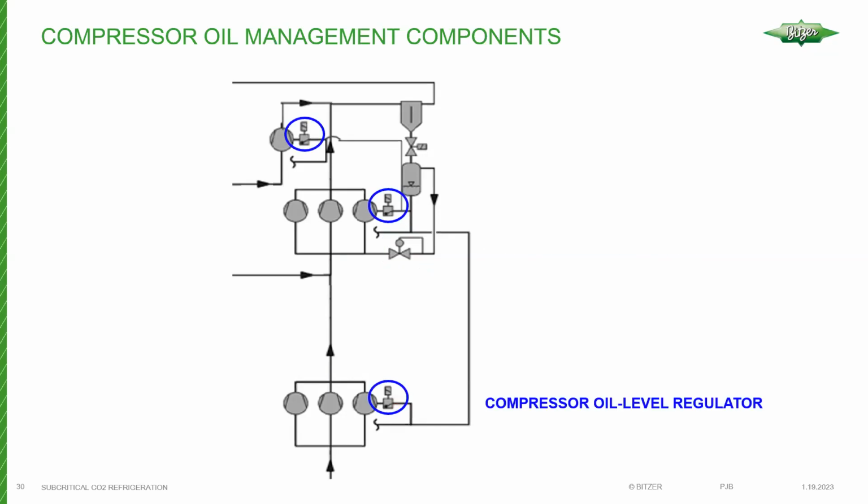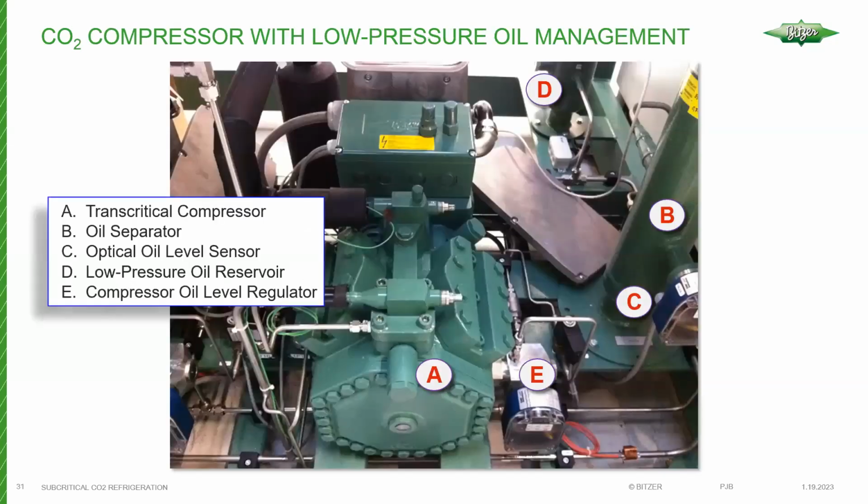And here you can see other oil level regulators installed. We didn't show all the regulators here. This is just to give you an idea. This is actually showing an oil level regulator on a parallel compression circuit on medium temp or high stage compressors. And then we have subcritical. But again, we'll talk more about parallel compression in the next session on February 16th. And it looks something like this.